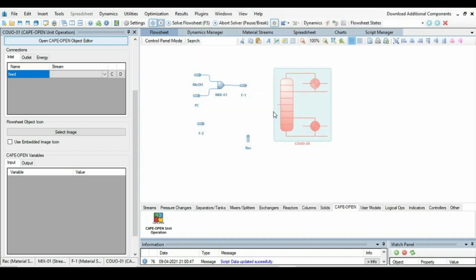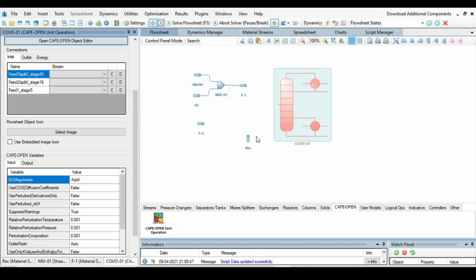Yes, you have to save them, and here I would recommend at this point just pause the flowsheet solver, because it will continuously try to recalculate every time you change any value, and it will slow down your process. I will solve the flowsheet in the end when I put in all the input data. I'm just disabling the flowsheet solver.